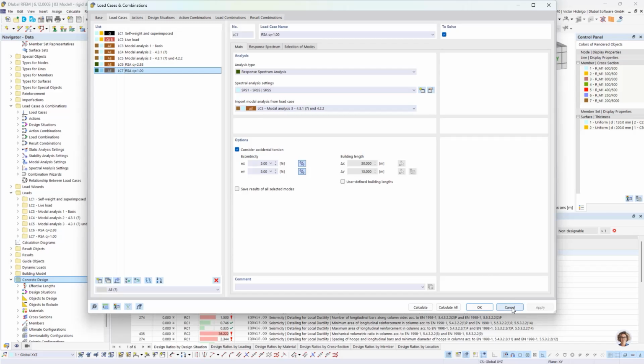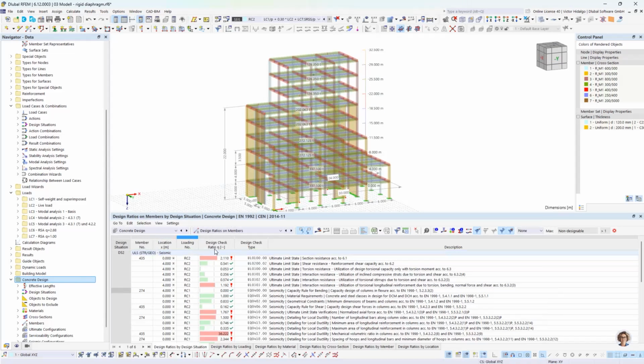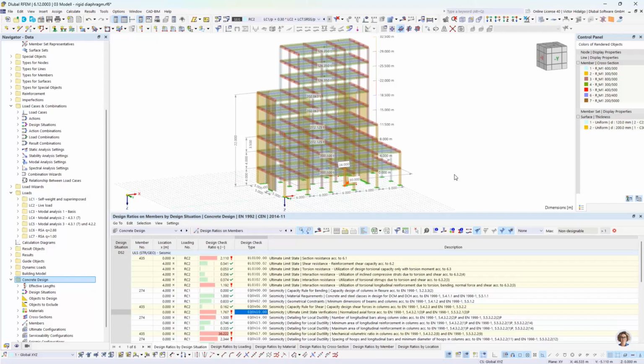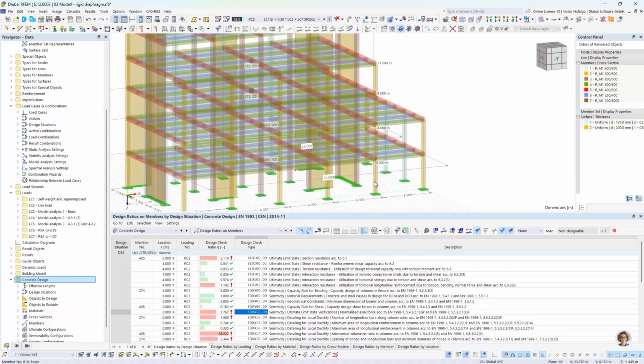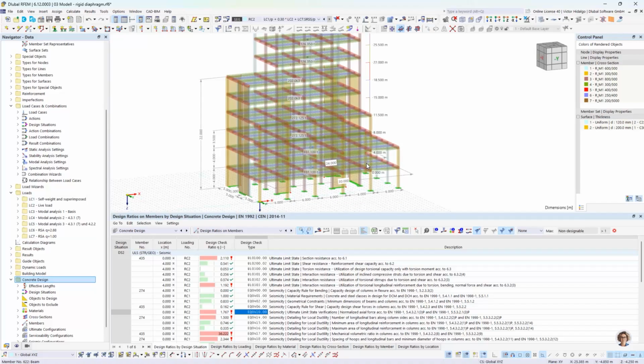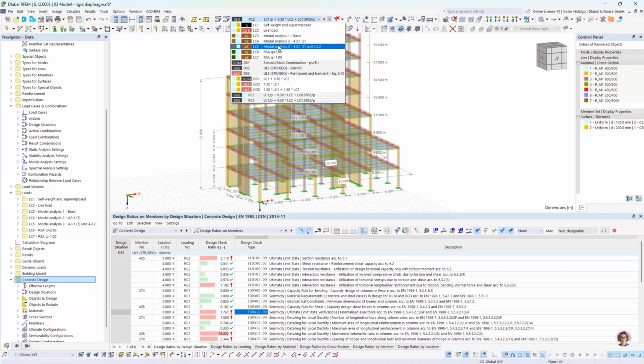As we have an example here, after this we have to make a design, and if we do not fulfill something here, we have to go back to change probably dimensions in the elements and carry out the whole design again. So if I make a change in the dimension of this column, then I have to go back and run again the modal analysis and the response spectrum analysis and perform once again the design.